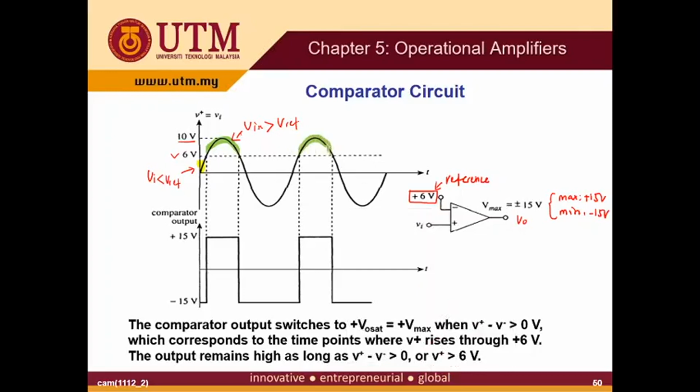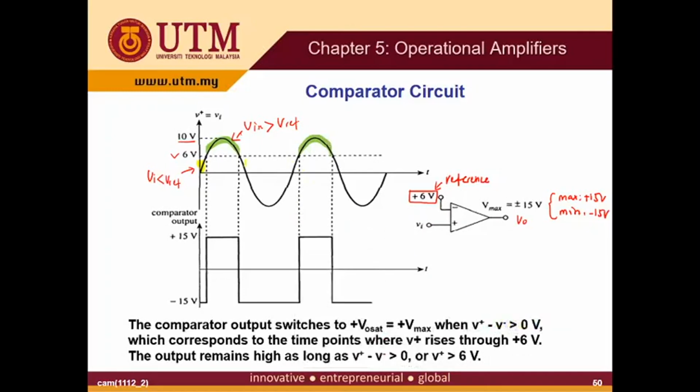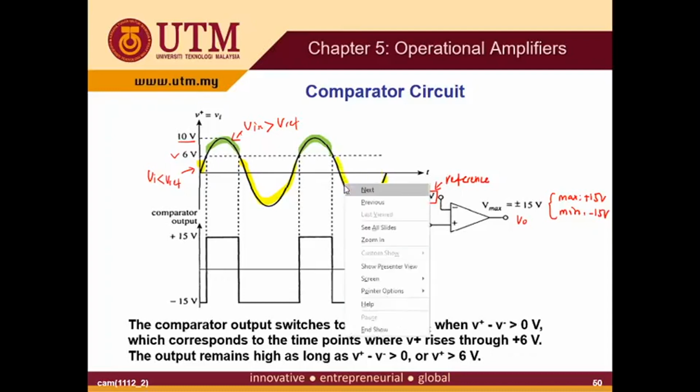This is also where the V in is larger than V reference. And then this is where the V in is lower than V reference. Once you have identified the regions, you can draw the output voltage.